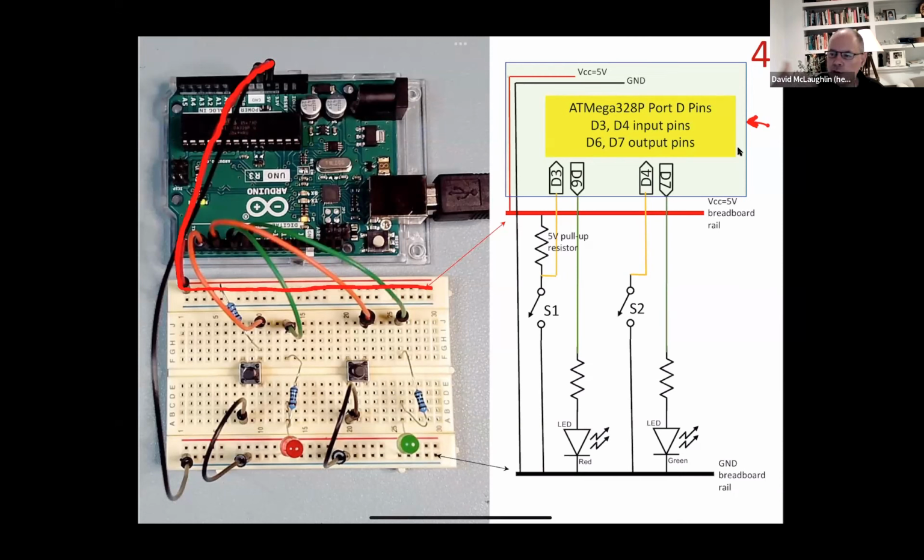And since it's closer to the red wire up on top of the breadboard, then by convention, we would call that our positive voltage rail. So that's our 5 volt rail on the breadboard. That's what's represented by that red bar, the way I've drawn it, okay? Then we have the black wire that's going to the ground rail on the breadboard, right? And that's what's shown down here.